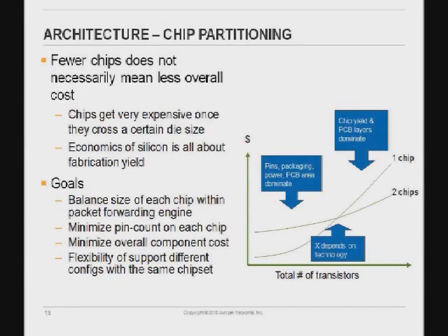And also, the ASICs usually use the periphery for inputs and outputs. And there's only so much peripheral area available on the die compared to the logic on the chip. So we have to balance the chips based on their input, output, and the ratio of logic you do in the system.